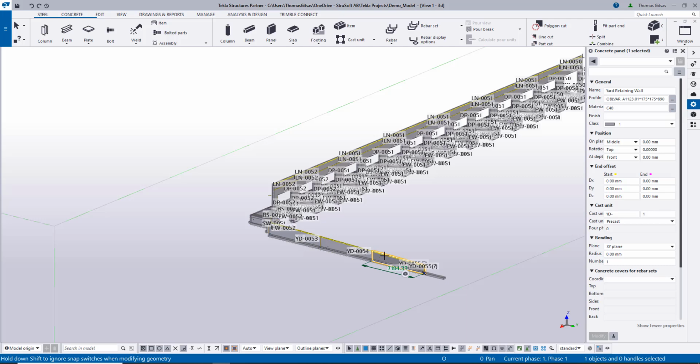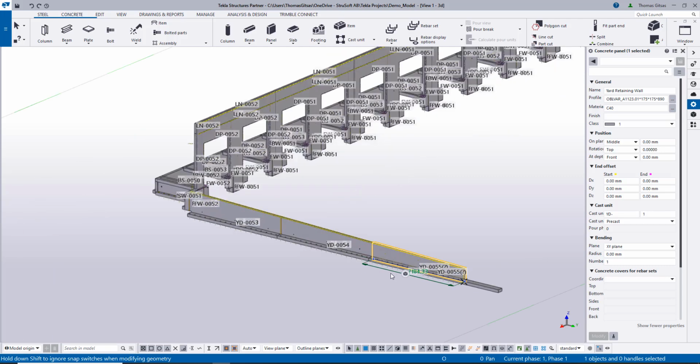If you just take this and modify it completely, then it doesn't matter even if you make it a smaller element change, as long as the GUID of the assembly is the same, then you only have to press update. If you change the GUID, then you need to link, map, save the element directly again from scratch.